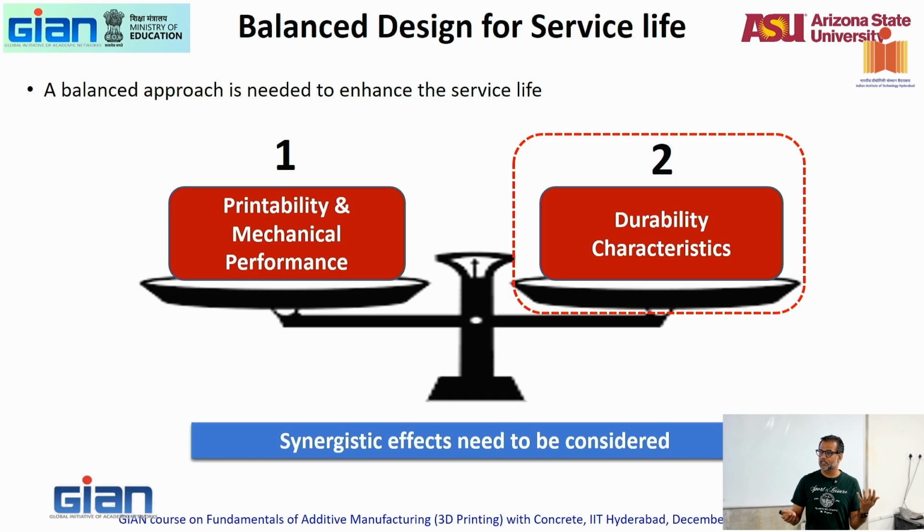The first order of defense is to make sure that your concrete is well made, well taken care of, good proper water cement ratio, good compaction, good curing practices, so that you can protect it against any kind of damage. So with 3D printed concrete, we won't talk much about corrosion because we don't really have enough data on corrosion of steel within concrete.